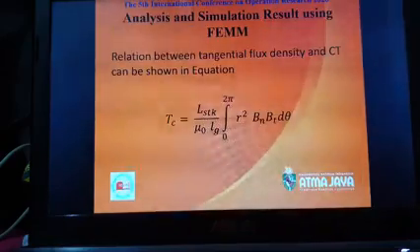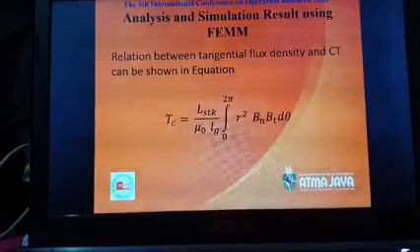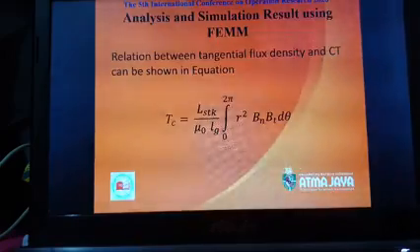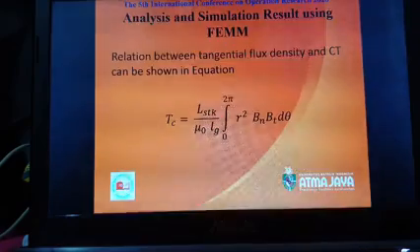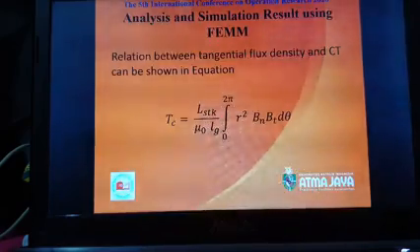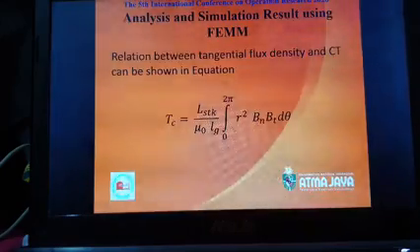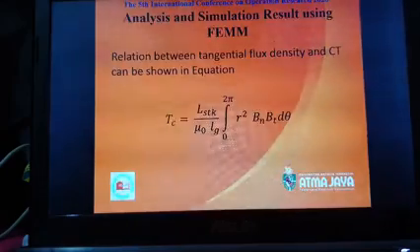It has been understood that the location of the tangential flux density is around the magnet edge. So, performing shaping on the magnet edge could reduce the tangential flux of the magnet effectively. However, the effectiveness of shaping the magnet edge depends on the type of machine.